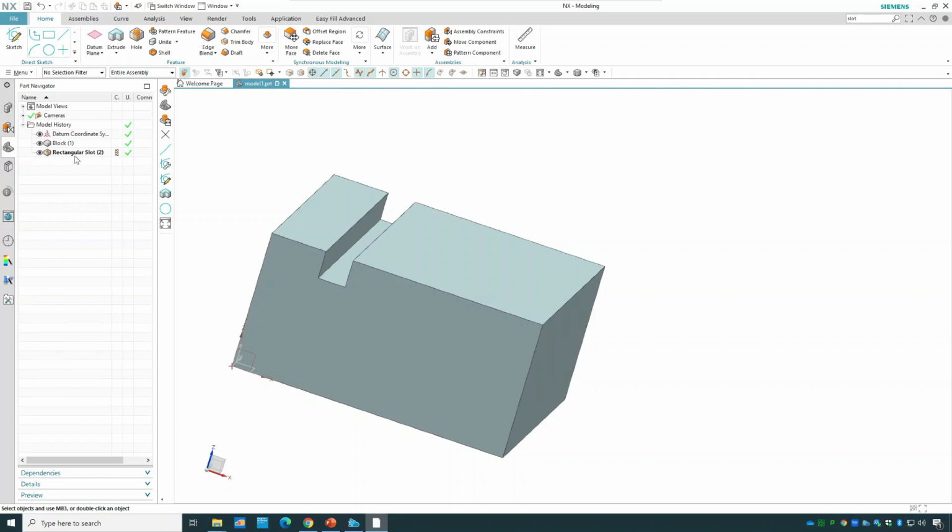So let's change the type of this one. Let me go there, go to the edit parameters. Let me change the type of it and go and change to the ball end. So it's like the grooving basically with the ball end. It's like a ball that goes through. You can put the ball diameter, you can put the ball depth.